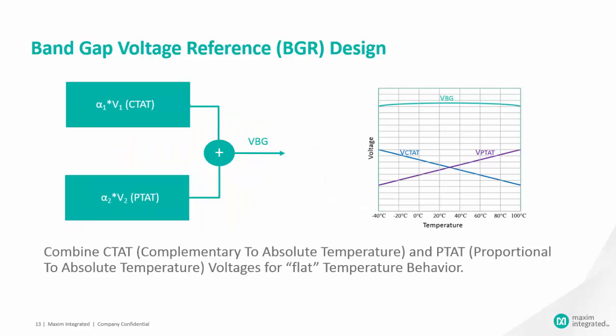Bandgap voltage references, or BGR, are the standard reference in integrated circuits due to their ease of integration, manageable value, typically 1.2 volts, and high performance. BGRs are built with standard IC components, that is, transistors, resistors, and amplifiers, hence they don't add cost or complexity to the fabrication process. A basic silicon BGR yields a 1.2 volt output with a very small tempco. Higher reference values, for example 2.5 volts or 5 volts, are obtained by amplification of the basic 1.2 volt value.